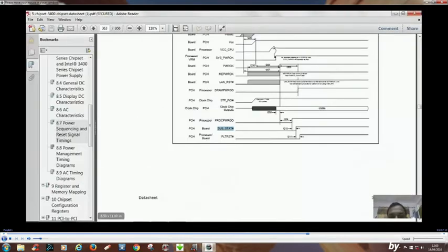Now we find the next signal, and the final signal is PLT reset. PCH generates PLT reset. PLT reset means platform reset, that is, all the other ICs including the processor will get a reset signal to start, right? Reset, what do you mean by reset? Reset is like a knob, you know, we press the reset button, then everything turns on.